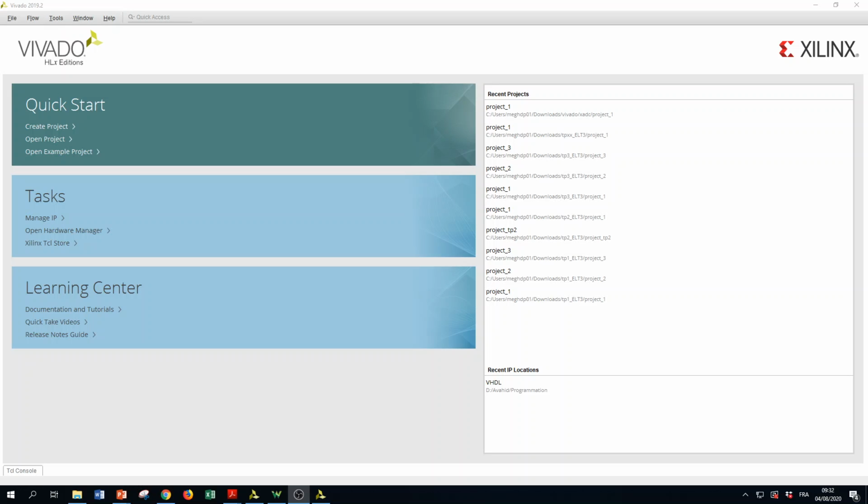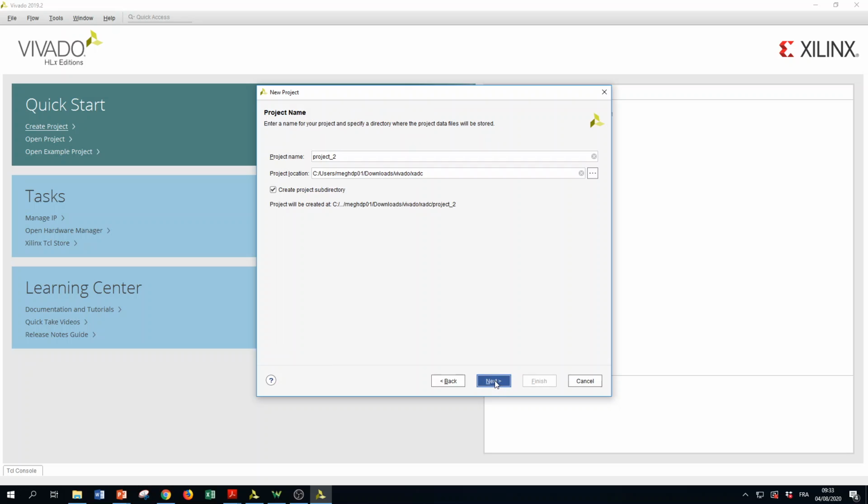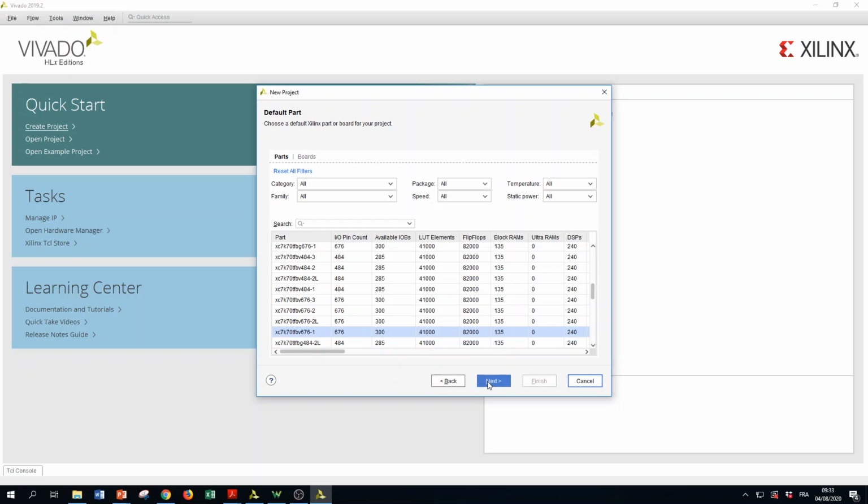Hello. So here I'm going to create an FIR filter in this tutorial, and I will use XADC to sample the analog signal, and then I will also use Analog Discovery 2 of Digilent to draw the Bode diagram of the filter. Okay, so at the beginning, I create a project and I create a component that will do the filtering. To be easy at first, the filtering is just a moving average, so it is very easy.